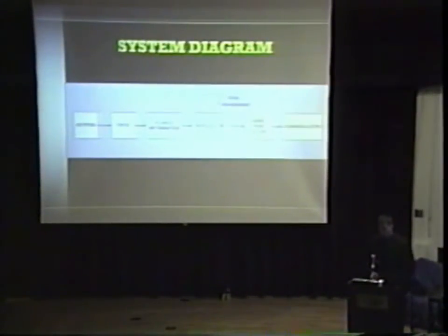This is a basic system diagram. The user keypad is the input to the digital system on the CPLD board. The source information is basically taking the digital information and producing a required voltage for the modulator, which will output an analog waveform sent through a bandpass filter and then demodulated again.